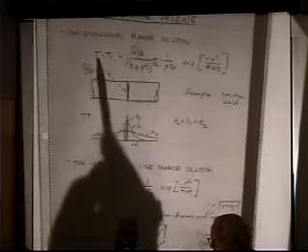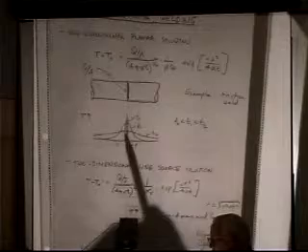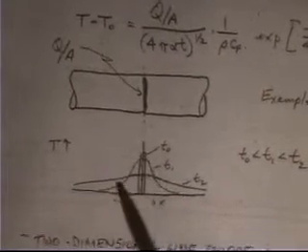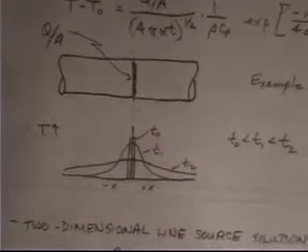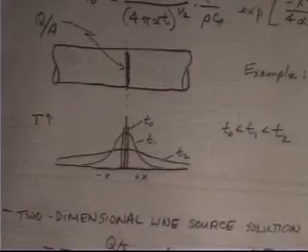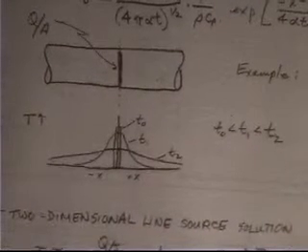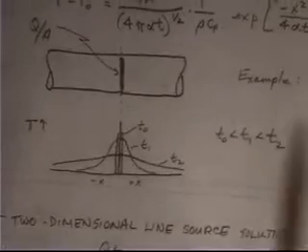And the solution is the temperature dies off, it starts out at some peak, and over time, or you make the weld in a friction weld, you turn it off, it starts out at T equal to 0, you've got a lot of heat at the interface, and basically it's just a Gaussian decay. And the area under that curve, which I haven't drawn very well, the area under these curves should all be the same, as long as I don't keep putting heat in there. And that's equal to all of this stuff.